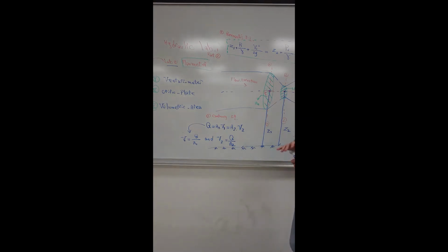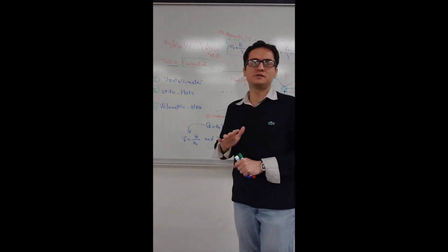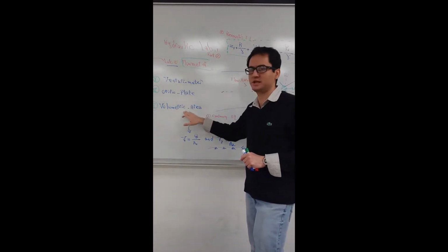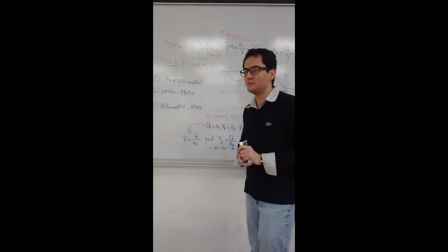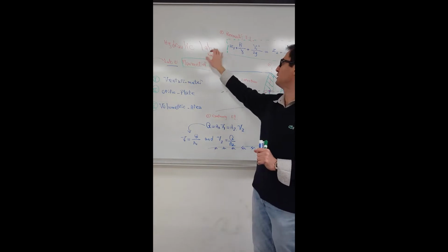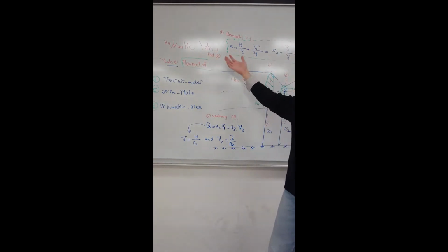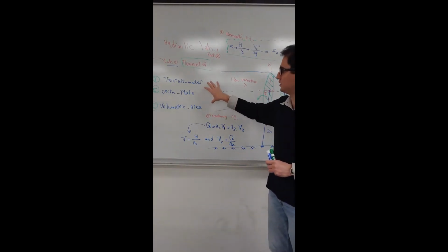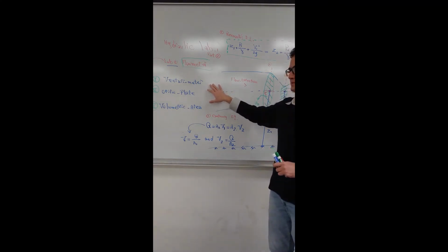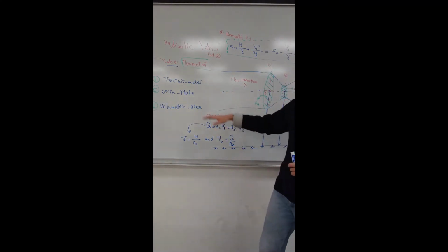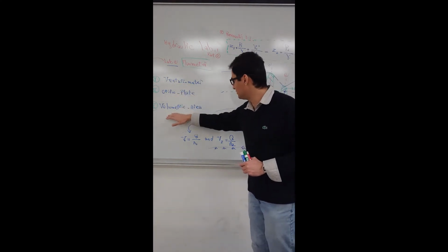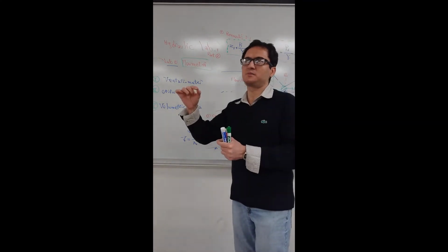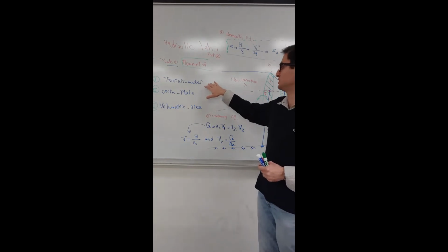Here we are going to talk about flow measurement devices such as venturi meter, orifice plate and volumetric area, which in the experimental part, the next session, Lab 1 Part 3, we are going to do that experiment. Now we are talking about their structure and their analysis first. So venturi meter, orifice plate and volumetric area are three sets of devices to measure the pressure difference, total head loss and also discharge.